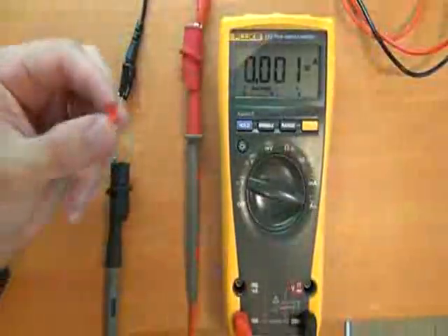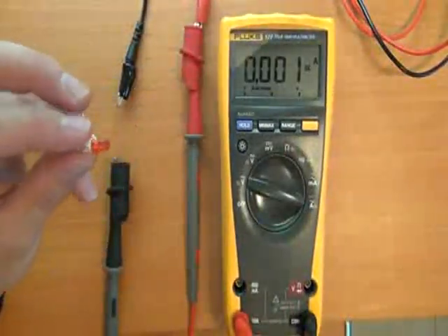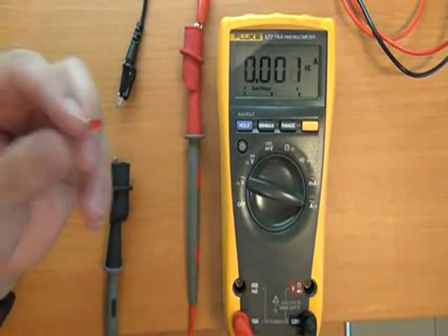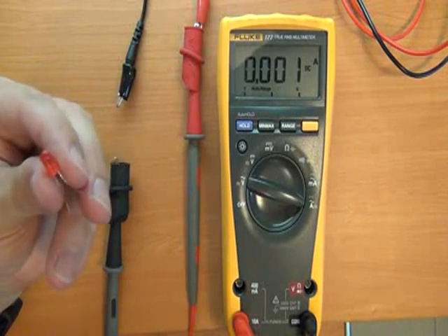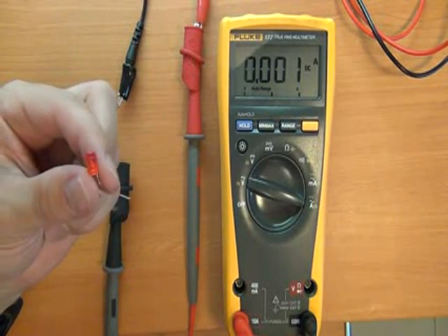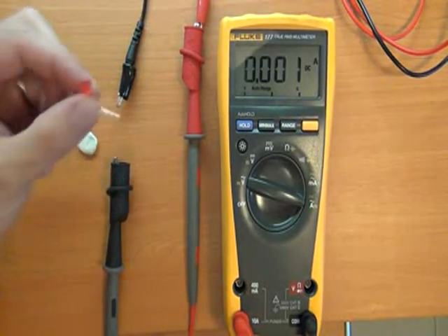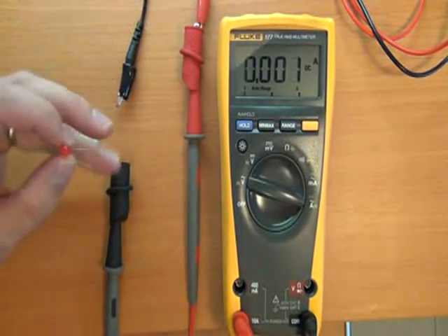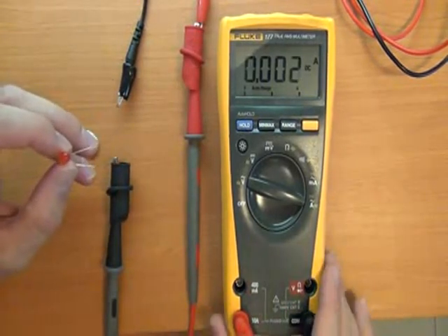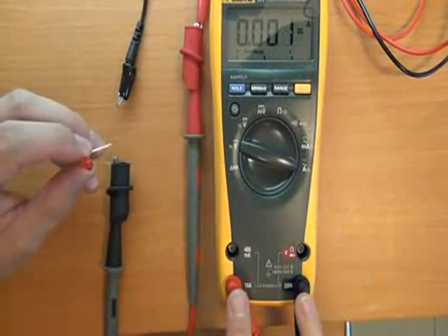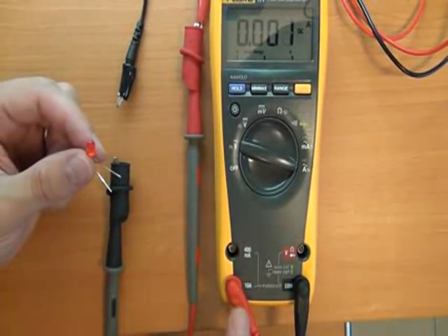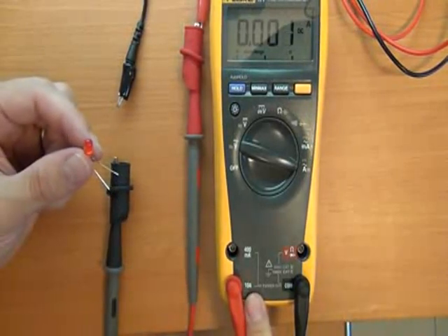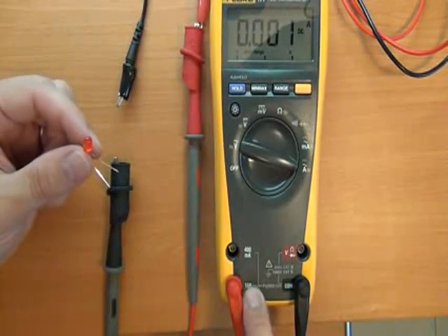Okay, so now we're going to do a measurement of the current, or the amperage, used by this little red LED. So I'm going to connect it up, and again remember, we've still got the multimeter connected in exactly the same way. Even though we know this is not going to use much, we're going to err on the side of safety. We've got it connected to the 10 amp connector here.